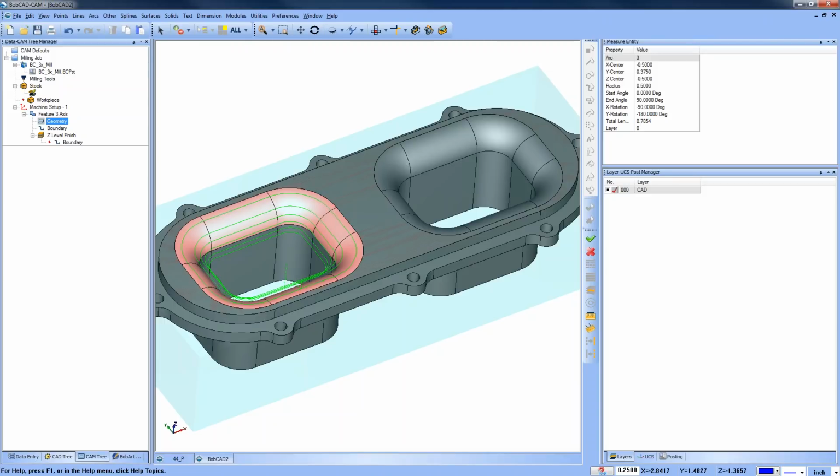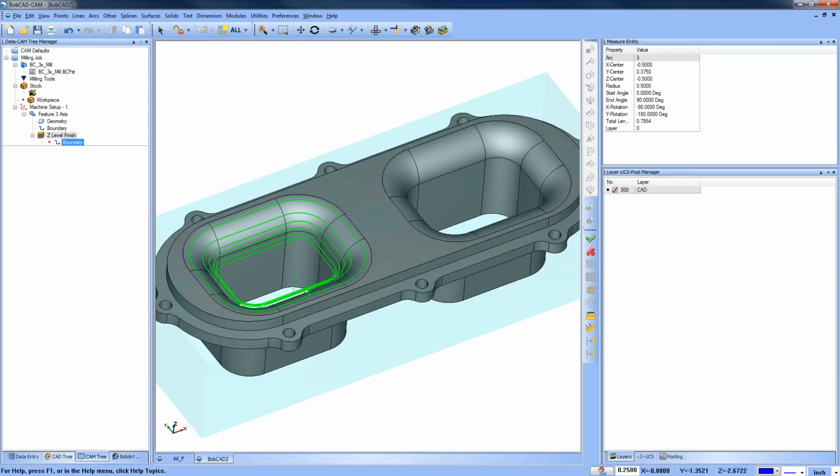Reginald, can you do multi-step with a corner rounder? That is actually a great question. I deleted it out, so I can't go in and check, but there are ways to accomplish that by using a toolpath pattern if it's not in there. Ken had a question: is it necessary to show the initial stock? Okay, when it comes to ZLevel Finish for mill standard, it is not a stock aware toolpath. If you're in the mill professional, you have stock aware toolpaths, so you could define the operation stock to help with trimming out unwanted moves, or some of the other toolpaths are stock aware.